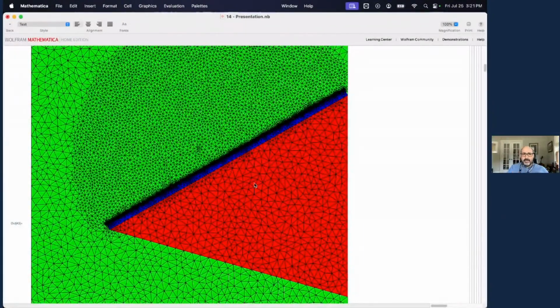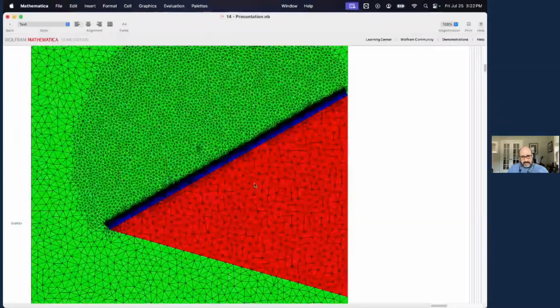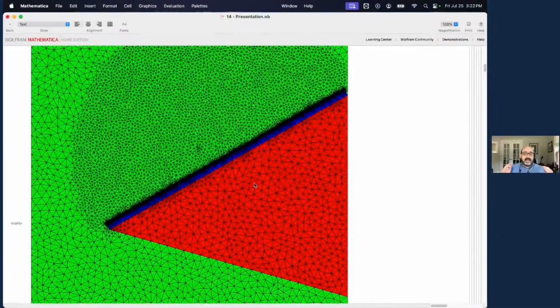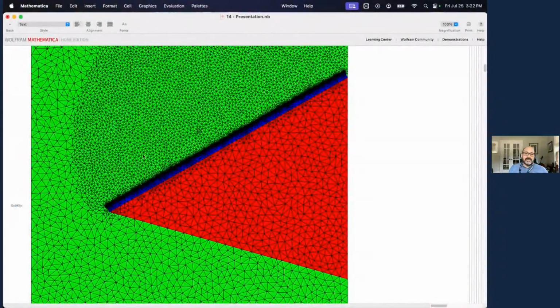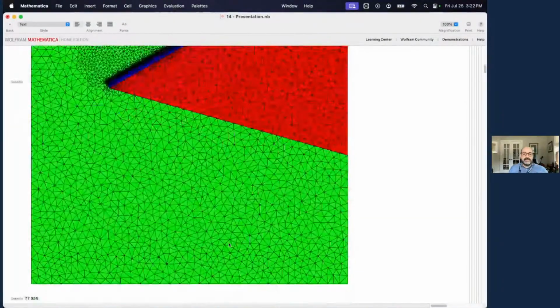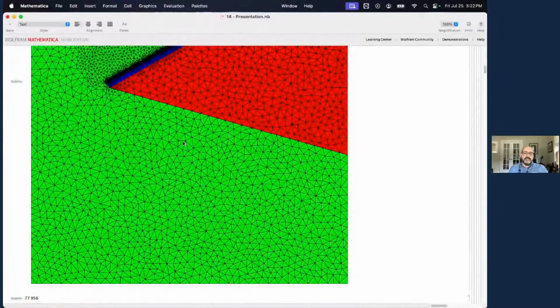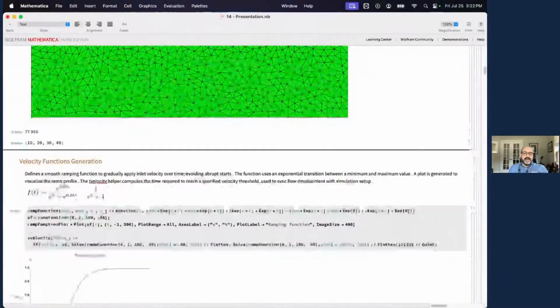Now, as I was saying, Mathematica will solve anything. The question is, how long will it take? And that's where you have to come in and ask, how do I optimize my technique? So why don't I care about this area? You can see the mesh elements: these are coarse, these are very fine. I get a very fine, refined mesh on the area where the interface is, because that's where most of the interest is for my research. Here, as you'll see later, I want to remove it from the mesh. The different colors represent the different characteristics of the materials.